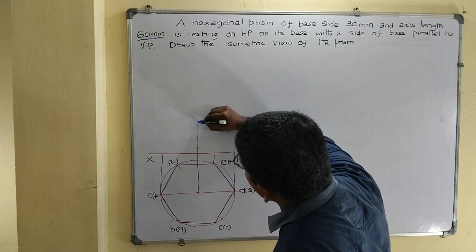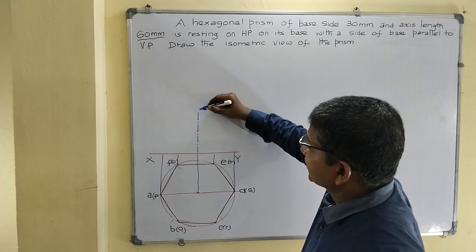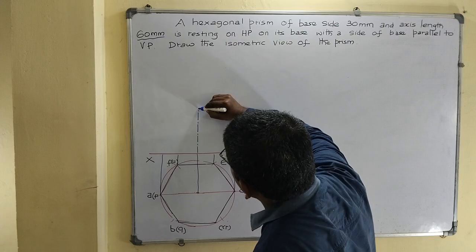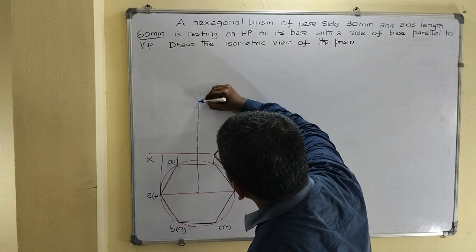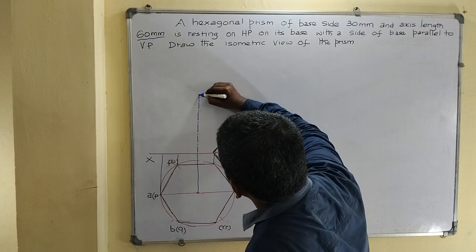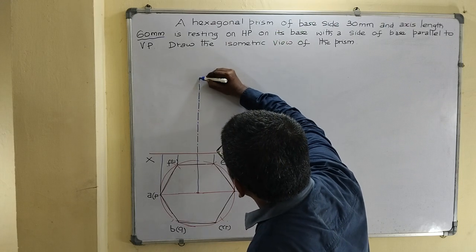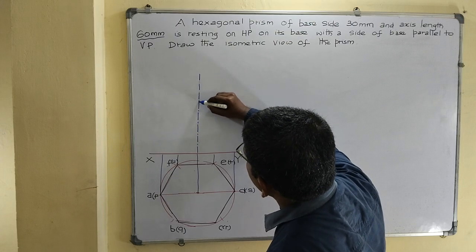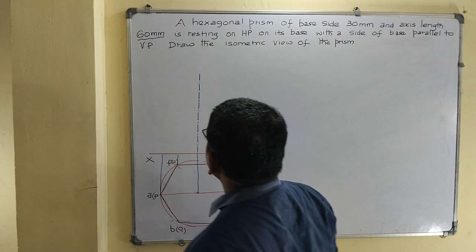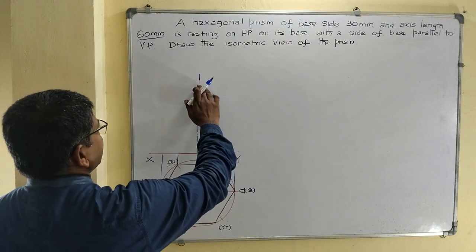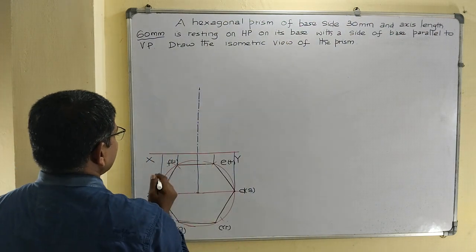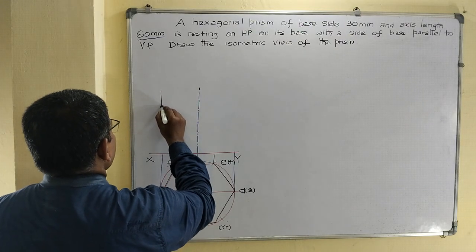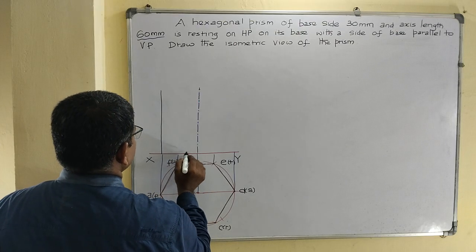How to draw the axis line? Using a 2H pencil, draw a long line 5 to 6 mm in length and one short line 2 to 3 mm in length, with a gap of 1 mm in between the lines. Extend up to 60 mm. Using the correct dimension, take 60 mm as the axis cut. Now complete the front view.